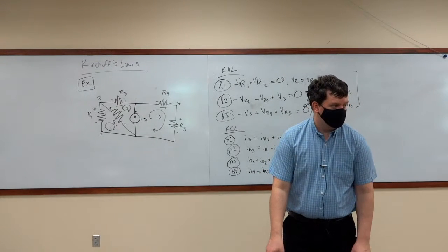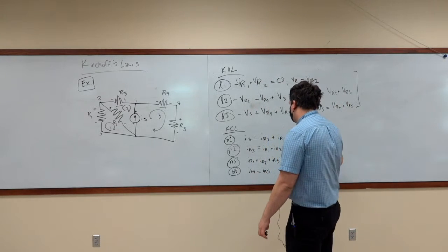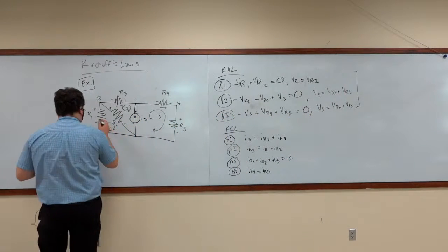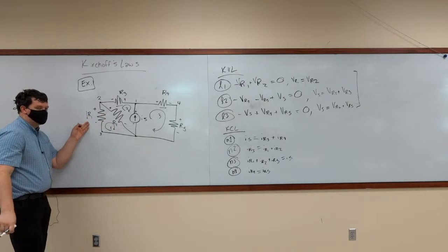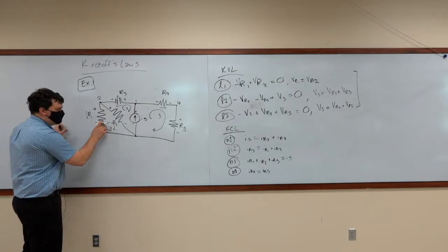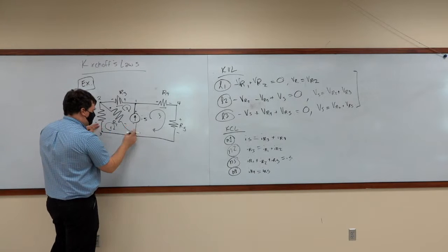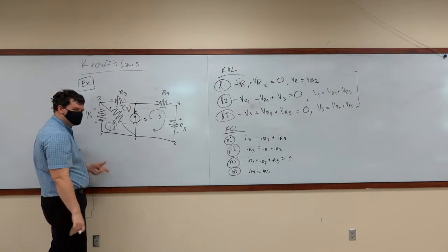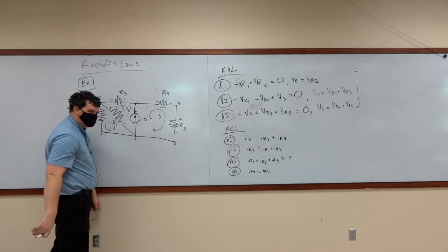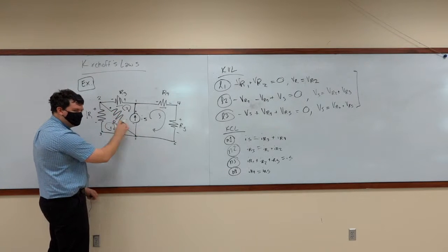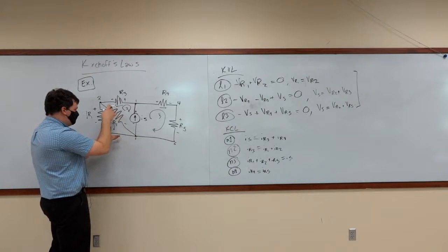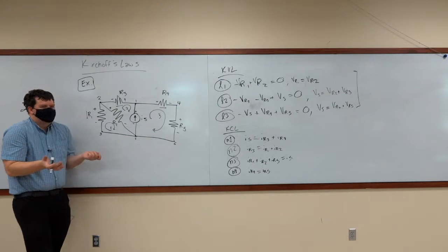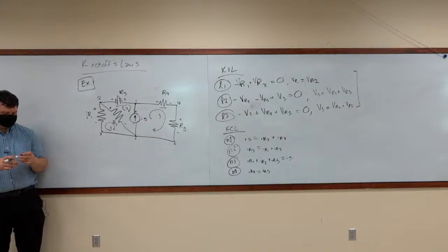Yeah. Can we go through where we got node 3 again? Yes. Okay. So, for node 3, we have this current that's running from positive to negative in R1. Okay? It goes into node 3. Node 3, we could call this, like node 5. We could call this node 6, but really there's no component that separates them. So 3 is equal to 5 is equal to 6. So here, anything that comes in to 5 will be also coming into 3. I know that seems a little counterintuitive, but it's because it's all one node. Does that help? Yeah, that helps a lot.